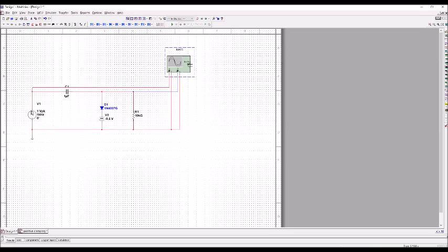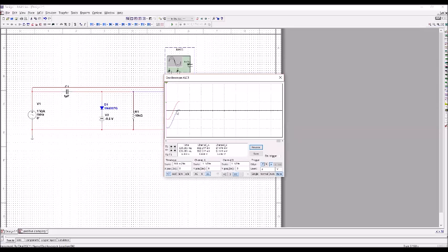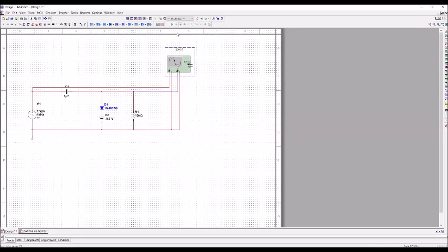And in the positive half cycle, this is an open circuit, and the current that flows through this will be a value of this, and also the charge stored in the capacitor itself, so it will be 2 times of that. So that's why we see that it is the same value, but here 2 times, minus 2 in this case. And this is a negative clamper.